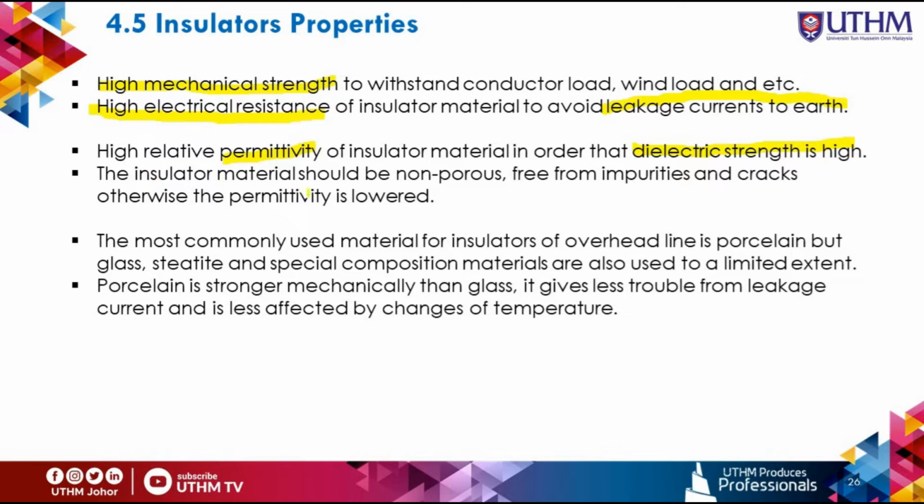The insulator material should be non-porous, free from impurities, meaning it must be clean, and free from cracks, otherwise the permittivity is lowered. The most commonly used material for insulators of overhead lines is porcelain, but glass, steatite, and special composition materials are also used to a limited extent.